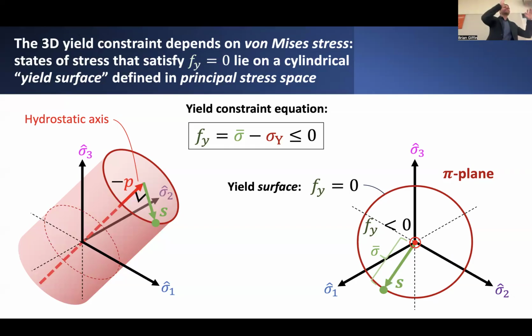Ultimately, when plasticity occurs, remember back to that one-dimensional idealized model. In that model, we had a spring in series with a slider. And we supposed that the elastic strain in the material was the only part of the strain that actually contributed to stretching of this spring and corresponded to the resulting stress in the material. However, the permanent deformation that occurs, the plastic strain in the material, evolves when I reach some critical threshold for the yield stress.